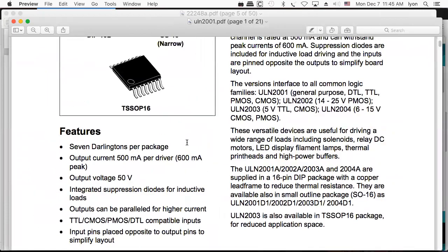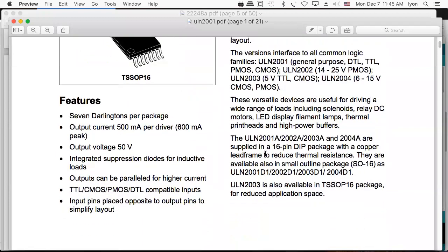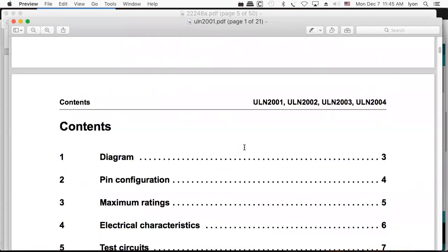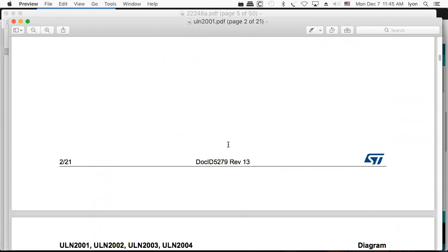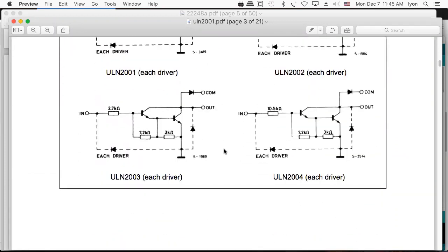All right, so what you want to do is start with the DIP and put another DIP on top of this DIP and then solder the pins directly to one another. And that will double the current that you can draw. You could always change the chip and get something that sinks more current, but we have these in the stock room. And if you needed an ampere out of an Arduino, put in these Darlington transistor drivers and that'll give it to you. You'll take an input like this and it will allow you to float the driver voltage. And so that's cool.